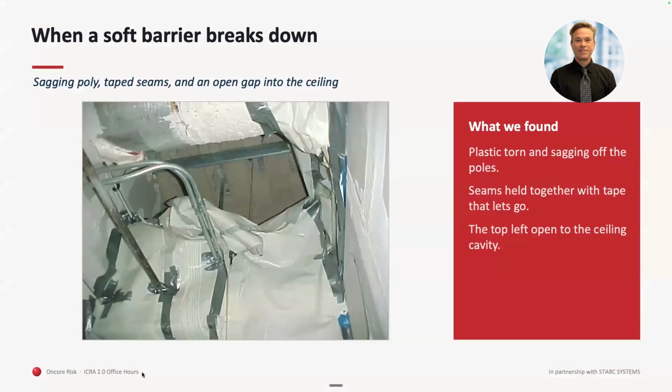So this is a good example of no protection at all. Maybe not the dust as much, but if you have a negative airspace, and another reason we put barriers up is to keep the space under negative pressurization. Well, this is a 6 mil or greater fire resistant plastic that's put up to the deck, and it's a challenge to keep these things in place.